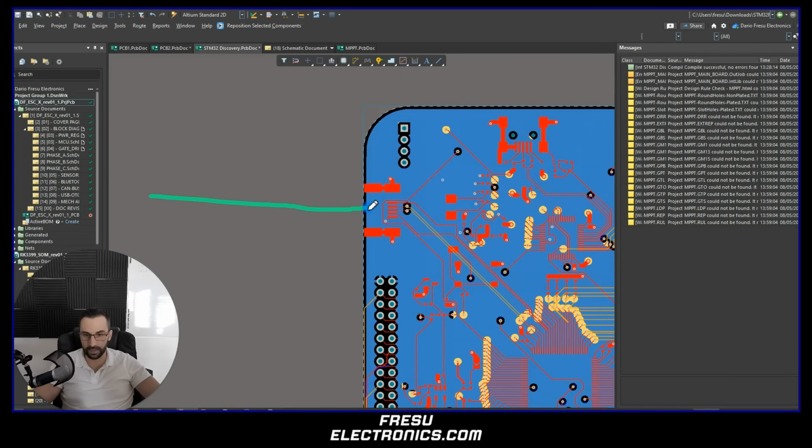So the same goes for this connector there. If we have in here a cable which is entering the board, then we want to filter as fast as possible. Before the signal even enters the board, we want to filter it and get rid of the interferences as fast as possible. But the same can happen when we have only output signals. So if we have output signals as well, we want to filter them before they go out from the board.